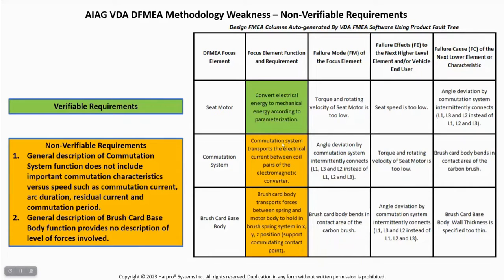And this is all about when you do a design FMEA. The purpose of the design is a big misunderstanding about design FMEAs. Because of its name, design failure mode effect analysis, everybody thinks it's about listing failure modes and assessing the impact of the effects. That's not what it's about. What it's about is assessing the ability of your design to meet these design requirements. This is a risk assessment of how good your design specs are at meeting these requirements.